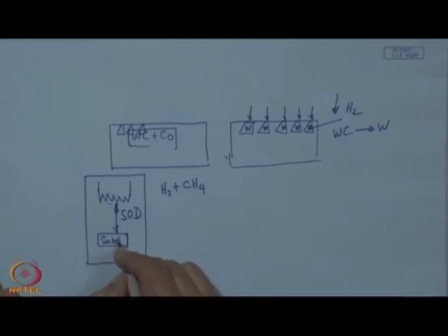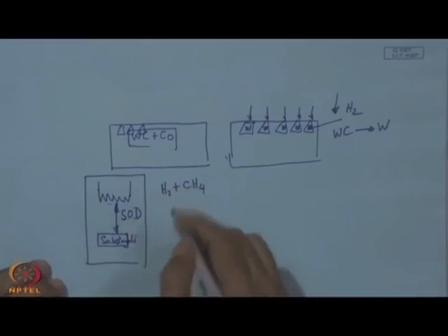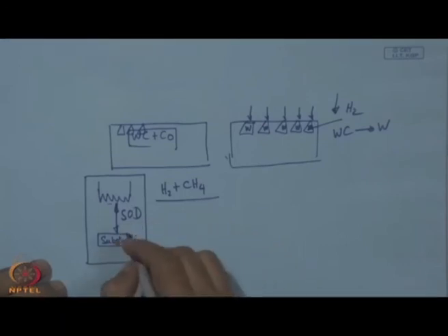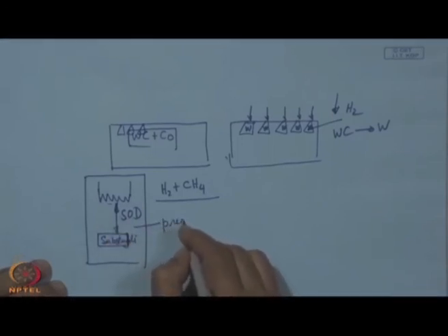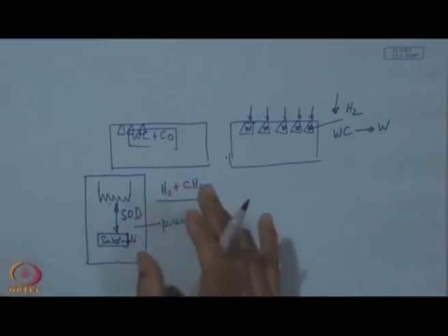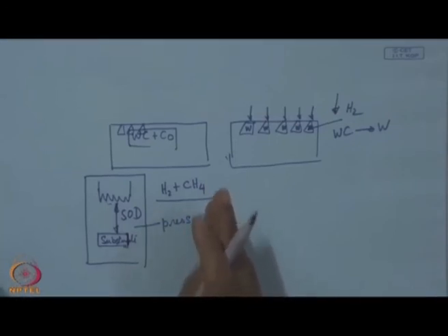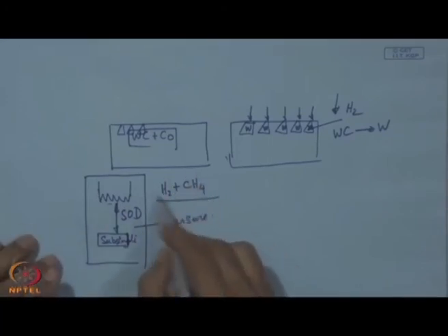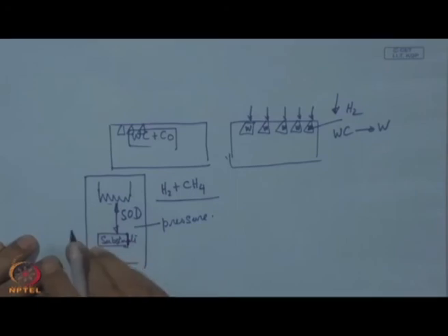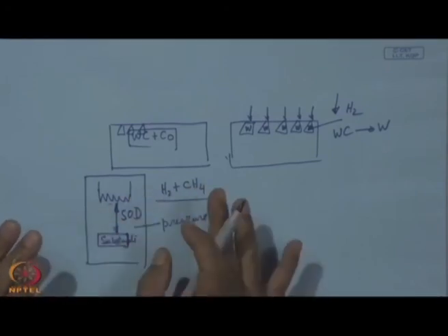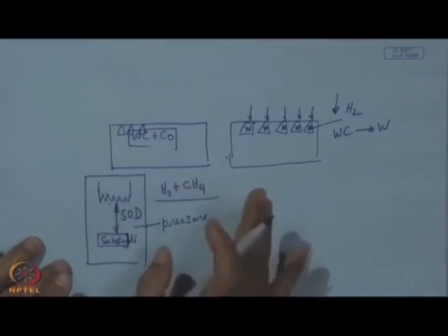This is the substrate. So, naturally the selection of this stand-off distance and the selection of pressure are not independent, and accordingly the pressure and the substrate target distance have to be also controlled, or considered in concurrence with the selection of the pressure. So, pressure and SOD have to be considered in their totality. The whole idea again is to have that impingement of this gas stream over this substrate with sufficient energy for the necessary conversion or structuring of the diamond morphology, and not to have unwanted collision midway, so that energy is spent or lost.